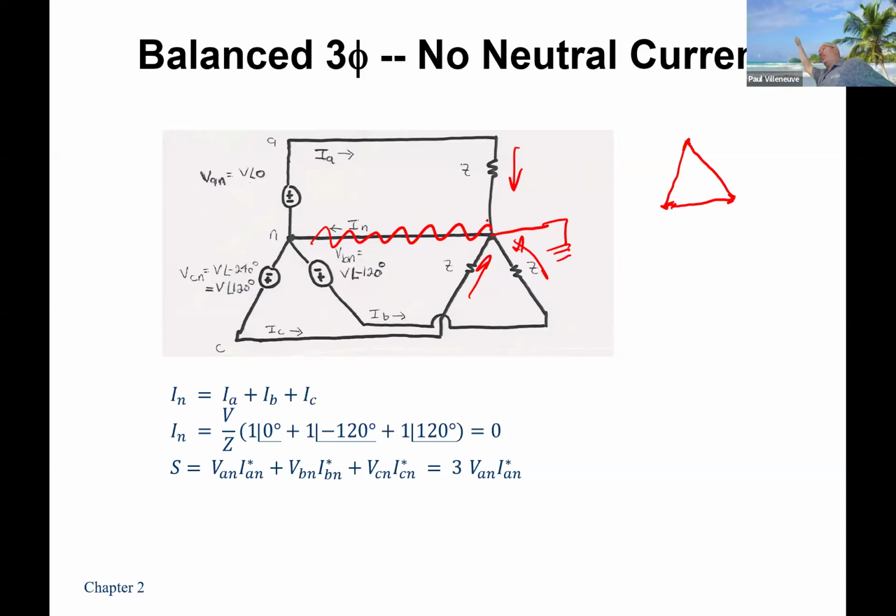So if the pole gets hit, it goes to that ground wire, and then it can conduct to ground. But it actually isn't necessary to run for a return path because we're standing on ground, right? Isn't that perfectly fine? And the other advantage is if it's a balanced system, no current goes to ground. They just travel back through their other phases. So in a balanced system, you have no neutral current.